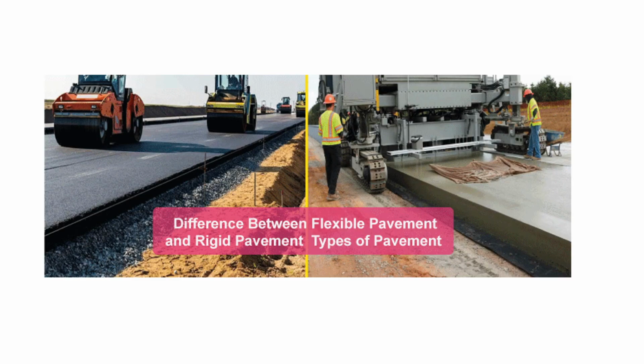Likewise, in the rigid pavement, the bottommost layer is a subgrade. Then above the subgrade, there is a granular subbase layer known as GSB. Then the DLC layer will come, dry lean concrete. After that, the topmost layer in the rigid pavement is a PQC, pavement quality concrete, right?